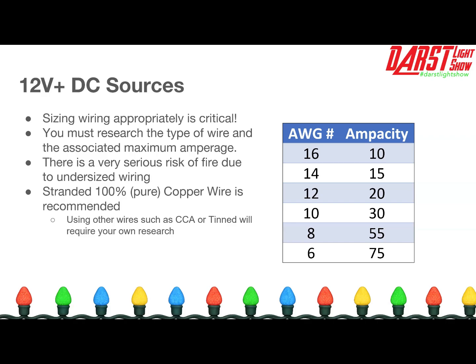Even if you put in circuit breakers, put in fuses, that kind of stuff, and you took the time to appropriately size those, I know you wouldn't use undersized wiring because you understand it all. But even if you did, those things fail too. So you don't want to rely on that kind of stuff to protect shoddy installs.